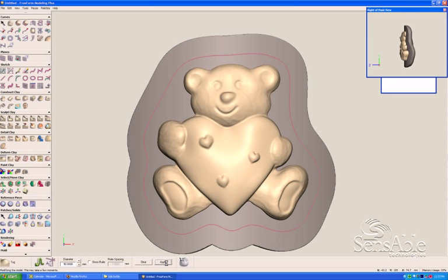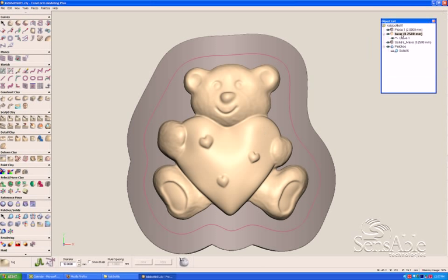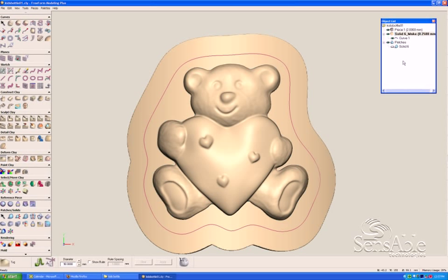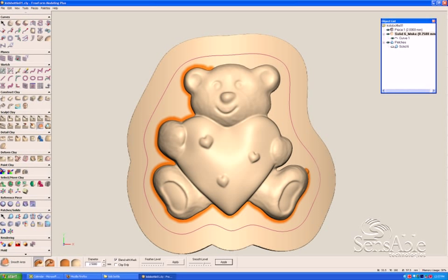Once we've done that, we want to combine the thickened part into the design of the bear so that we have one piece. We can do that easily through the combine into Boolean technique on the object list. That's a very simple function in Freeform, as opposed to doing Booleaning and shelling and things like that in CAD, which can be very difficult and frustrating because of the innate problems with those types of functions with surface and solid data. But since we're working with a completely different geometry called voxels, those types of functions work very well in Freeform.